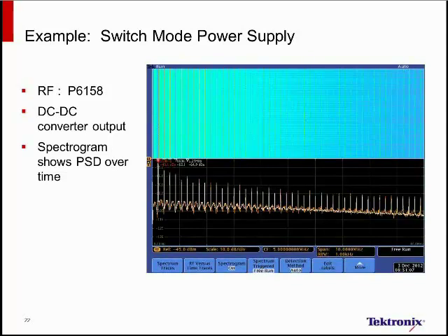But what I can also see is banding horizontally in the spectrogram display. That tells me that there's broad-banded energy there that is varying over time. It's not consistent, because if it was consistent, I would see a consistent color shift. But I can see these horizontal bands, and that means it's changing.